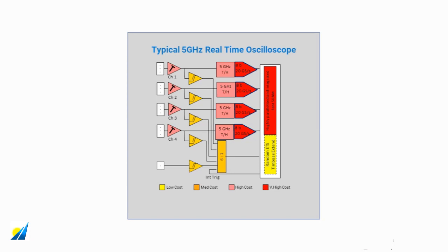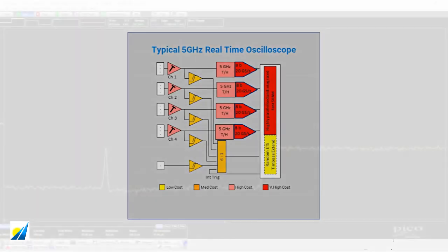And to that we must add switched gain amplifiers just before the track and holds and the trigger pick-offs. Those in themselves are relatively high cost. So overall the real-time oscilloscope package is quite significantly more expensive than the SX-RTO. Of course it is those 20 gigasample per second A to Ds that give the RTO a much higher speed or single event capture capability.